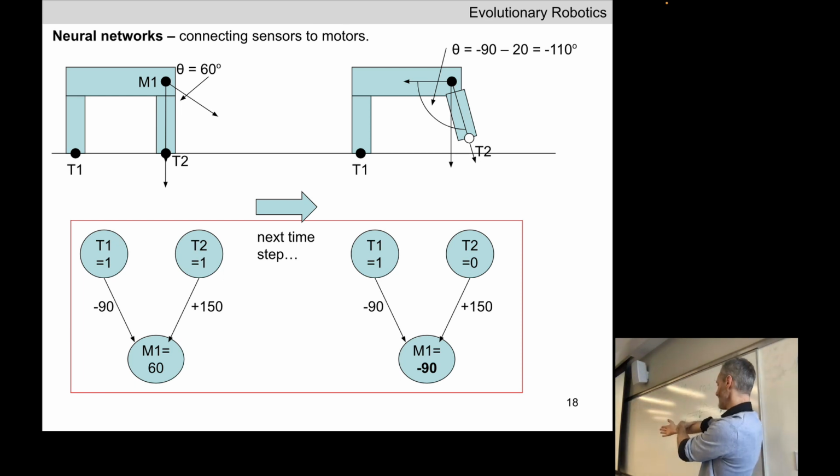Or if this is link 1 and this is link 2, they're going to rotate through the YZ plane. What's the joint normal we need to define for that to happen? 1, 0, 0, right? So here's X pointing in or out of the board. If I define this joint normal, these 2 points will rotate through the plane defined by the whiteboard here.